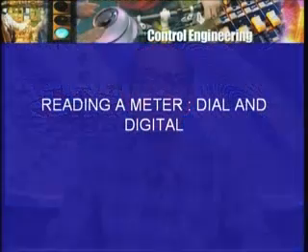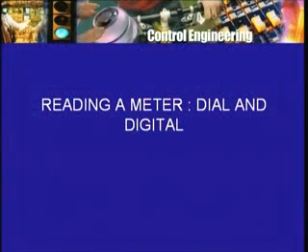The current may be 1 ampere, but within 1 milliampere. This is because of the nature of the instrument, the dial reading on the dial, or if it's a digital display, the number of digits in the display. If you set it up in the ampere mode and it can go up to 3 places of decimals, then a milliampere is the lower limit. You can't go lower than that.